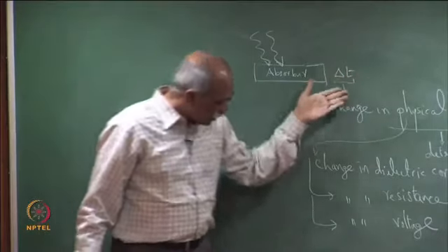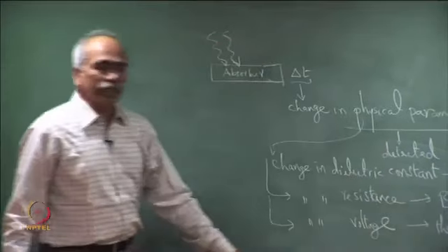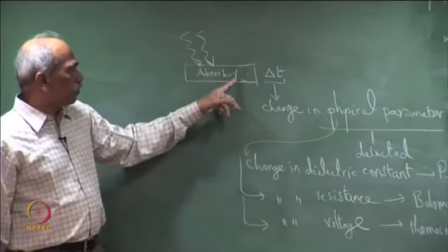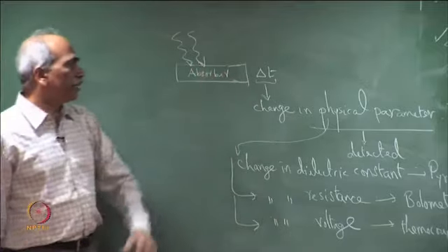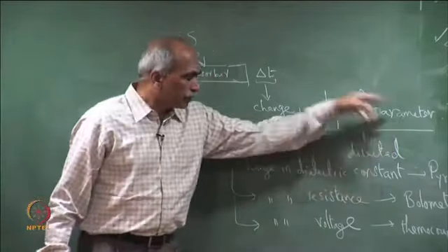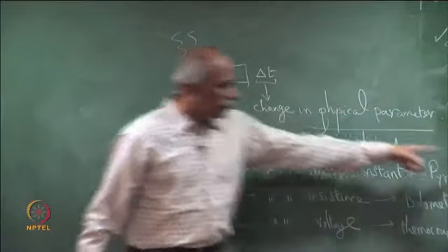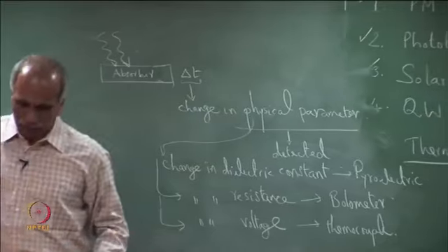So, the change in the physical parameter is sensed by different techniques, but the basic principle is just that incident photon flux leads to a change in temperature, which subsequently changes a physical parameter that is measured, and hence all of these fall under the class of thermal detectors.